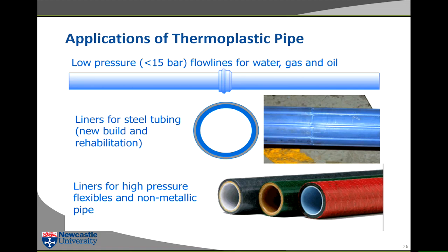You'll be impressed. But the key component in those pipes, the thing that stops them from leaking, is the thermoplastic liner. So I'm going to talk generally about thermoplastic liners, but there's one technical problem with all of these thermoplastic liners, and that problem is that gas can diffuse through the wall of the liner.